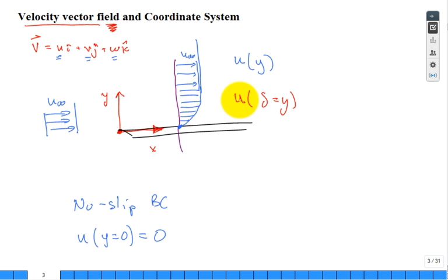So evaluate u at delta, which is a boundary layer thickness, delta, which is basically how far out I have to go in the direction y, such that I'm not 100% to u infinity, because I'm starting at 0, but I'm getting close. And now how close is close? Well, I'm very happy to report that vast majority, I've never seen any fluid mechanics textbook, although I haven't done an exhaustive search of this, that says anything but 99%.